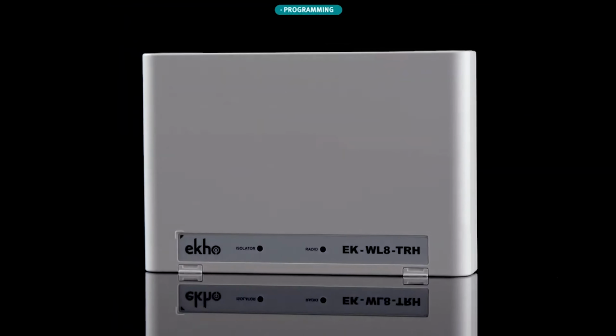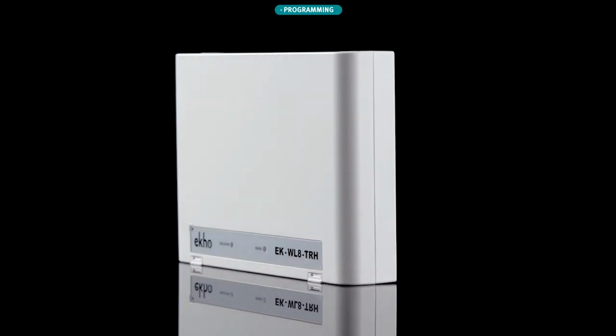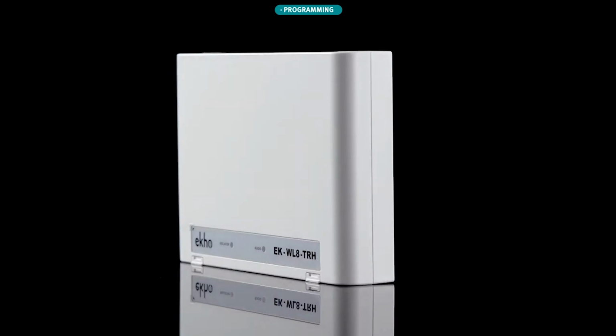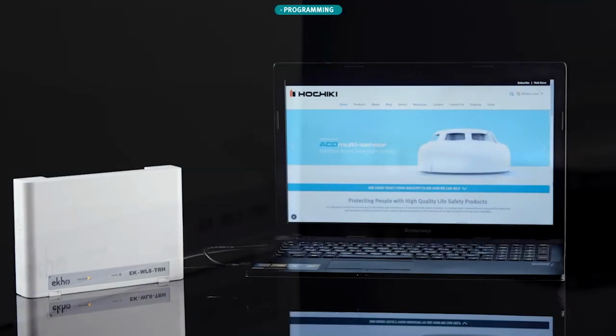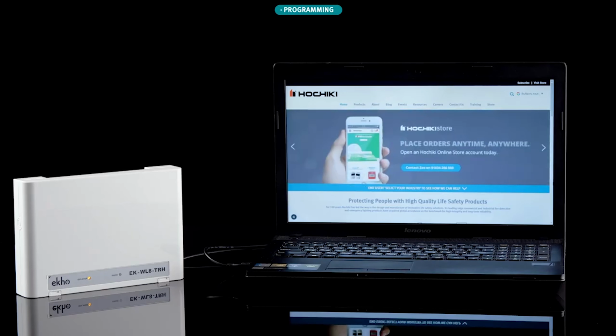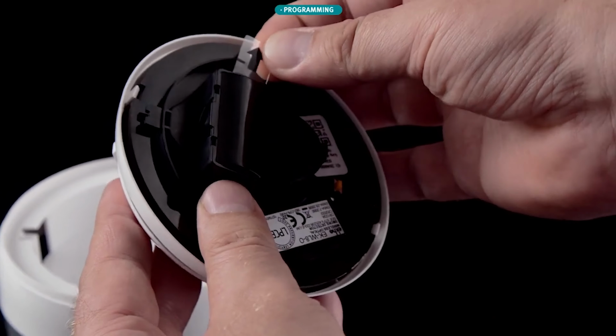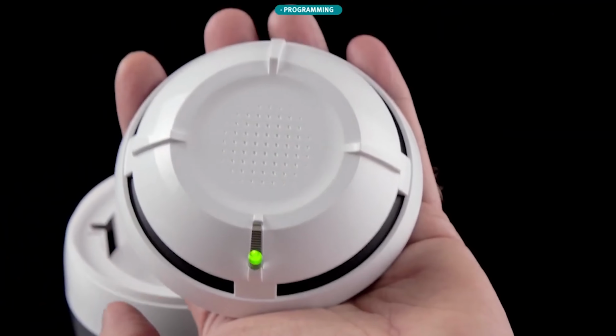Wireless expanders and devices can be programmed to the EK-WL8-TRH via the Ekho configurator software or via the menu of the translator module itself. Connect the translator to a laptop using a micro USB cable. As an example, the following explains how to program the wireless optical smoke sensor EK-WL8-O. Prior to programming, the sensor should be powered up. Remove the sensor from its base and remove the battery isolating tab before refitting to the base.